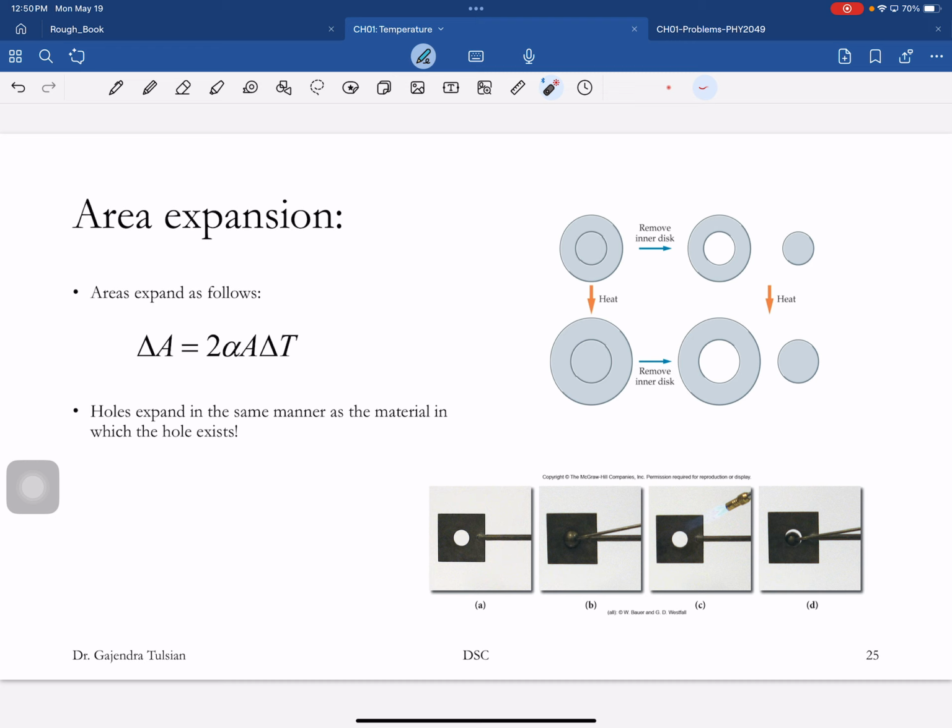You make the socket size, and you make the screw just slightly larger. But the problem is going to get worse. You try to screw that, and you're going to strip it. So what do you do? Take the screw, dip it in liquid nitrogen, and then put it in.